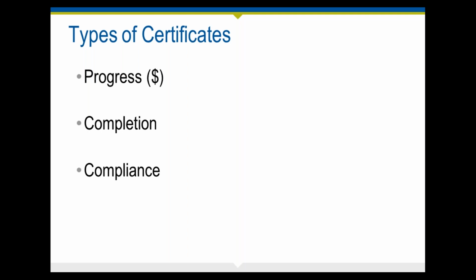So substantial completion dates are important because generally they determine, okay, if it's substantially complete, if there's any retainage being withheld, generally that's the date on which that can be released to the contractor. The warranty period begins. Oftentimes the equipment that's been put in place and so on does have a warranty. Those dates could start running at that point. Also the warranty obligations that the contractor has provided. If there is a delay, the date of substantial completion determines the actual or liquidated damages due to the delay in the project. And also, of course, it means that the statute of limitations and the statute of repose, those start running at that point.